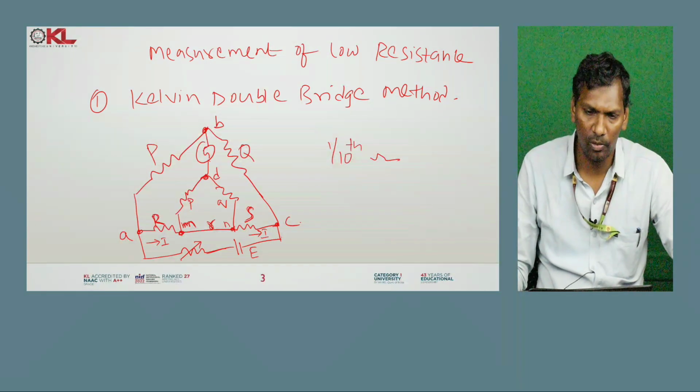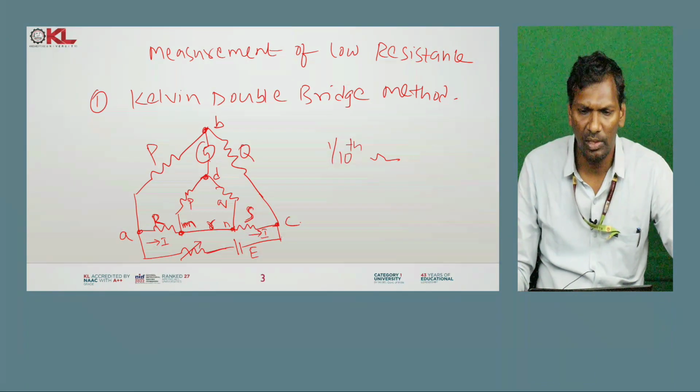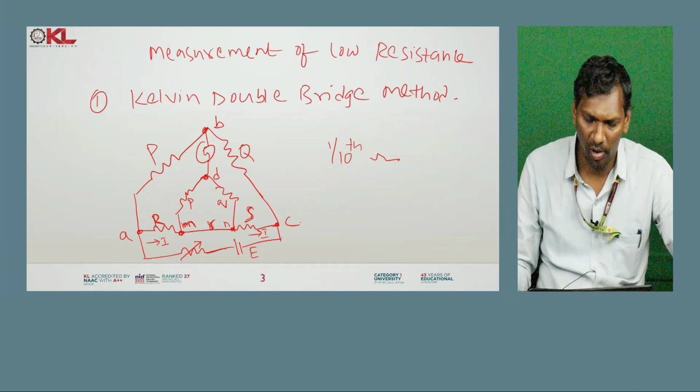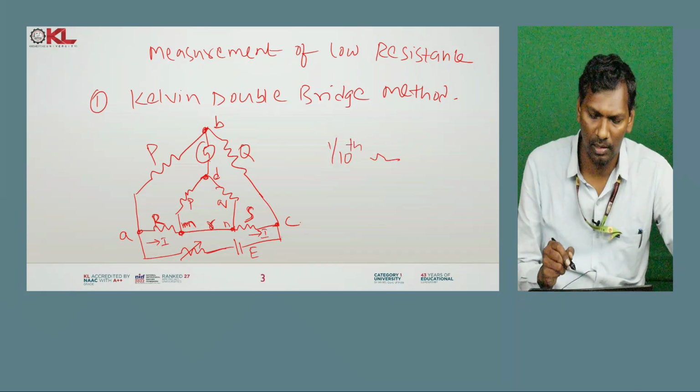When the galvanometer is connected to point M, the resistance r of the connecting leads is added to the standard resistance S, resulting in too low an indication of the unknown resistance R. When the connection is made to point N, the lead resistance r is added to the unknown resistance, resulting in too high a value for R. Suppose instead of using point M, which gives a low result, or N, which gives a high result, we make the galvanometer connection to another intermediate point D.